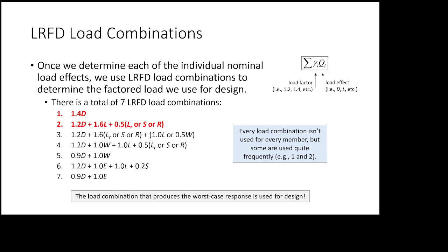But each of these load combinations are intended for different, what I would say, conditions of the building. So like, for instance, load combination 7 is for the building under extreme earthquake events, right? But really sort of when the building is evacuated. Load combination 6 is for earthquakes, but when the building still has like some people in it and whatnot. And there's a little bit of deceptiveness inside that because actual seismic loads and seismic analysis, there's a lot that goes on there. So there's a little bit in the background that's not really reflected.